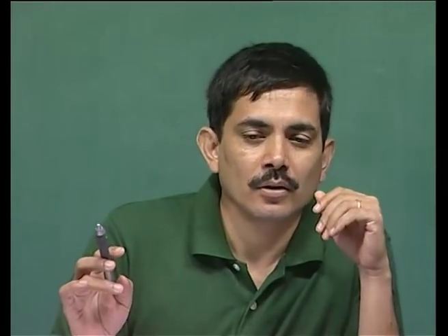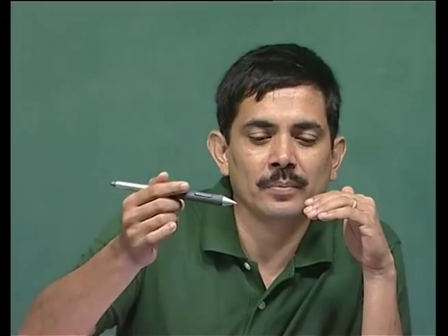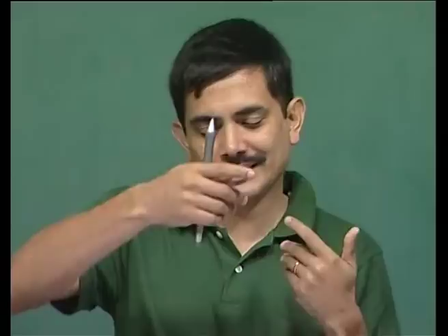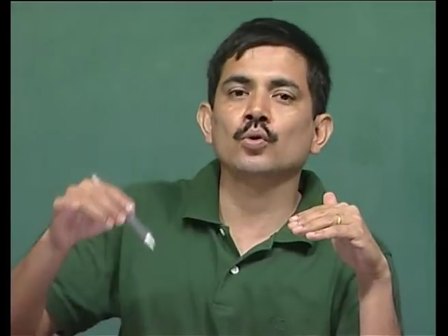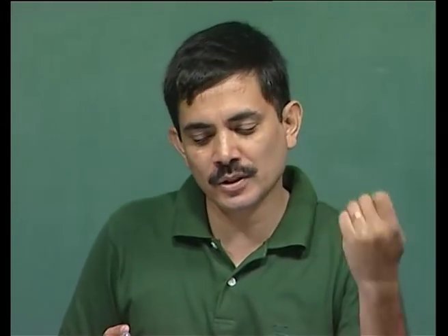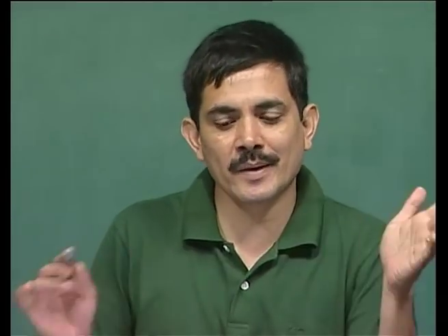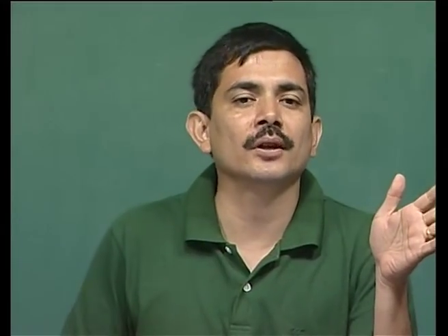Where do you use P controllers? You use P controllers where you really do not care about offset. A very common example is level. In a tank which is just a surge drum, you really do not care whether the level is 50%, 55% or 45% or 60% or 40%, as long as the level is between 25 and 75%, you are okay. So, for this type of system where the level is allowed to float in a range, offset is acceptable. Because offset is acceptable, the simplest controller that will give you reasonable control performance is a P controller. Simplest is best, therefore, level is typically controlled using P controllers.